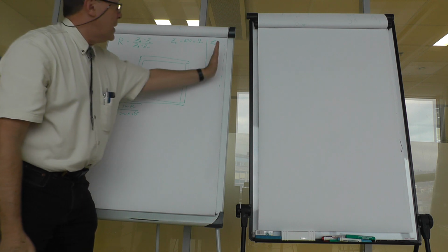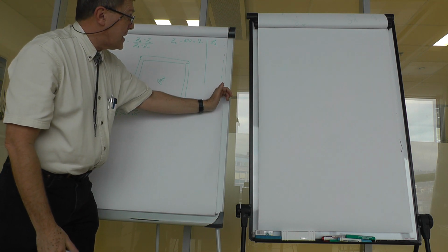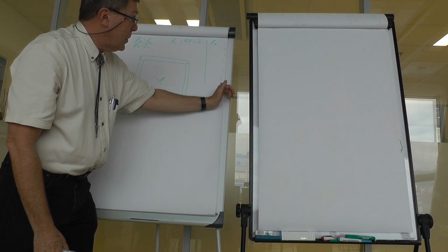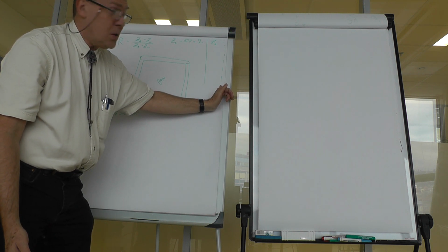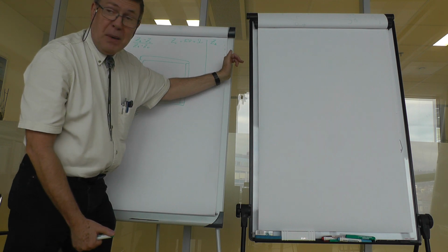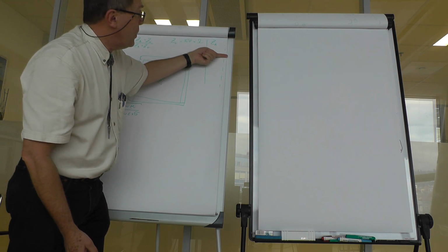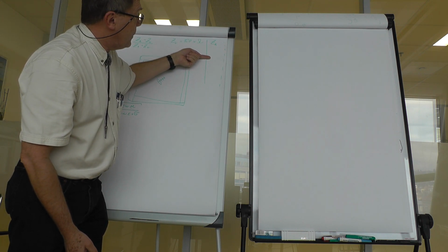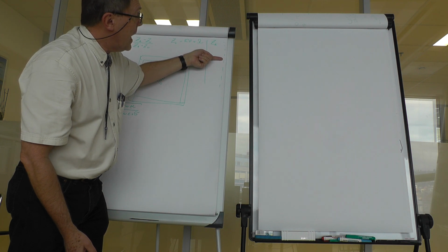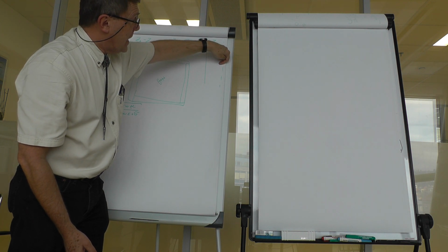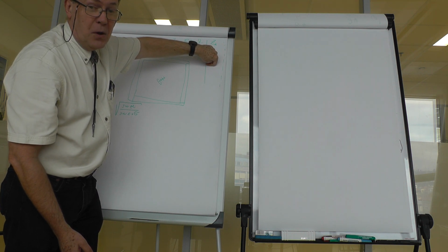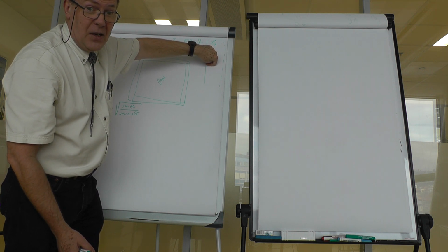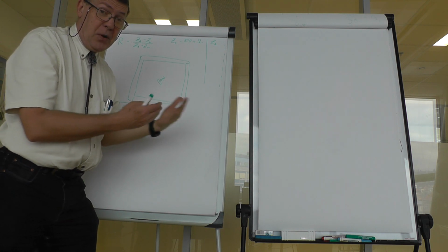So, for example, think about that as a simple termination, which is a metallic, an electric wall. So the reflection after that is big. Just we have to attenuate the wave so that it goes through the layer, attenuates very much, and if it gets reflected, it does not make it out of the layer with a significant energy. That's the trick we do in practice.